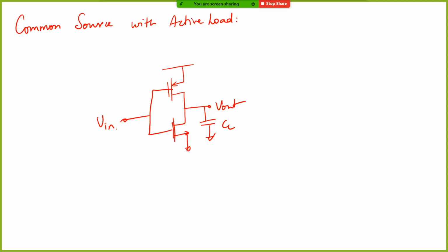What is the circuit? Sir, inverter. Exactly. It's a digital inverter. Now, a digital inverter has a voltage transfer characteristic like this, right? So, Vin and Vout. When Vin is 0, Vout is at VDD, and when Vin is at VDD, Vout is at 0. So there is this in-between region where the transition is happening.